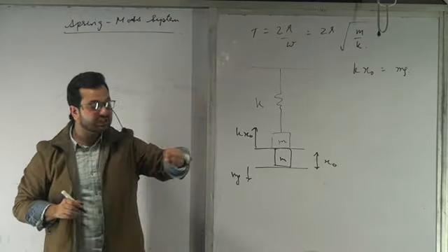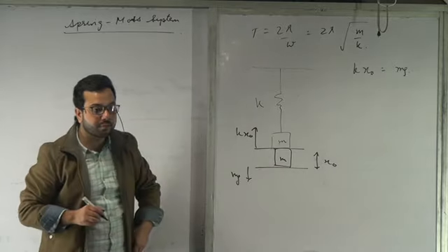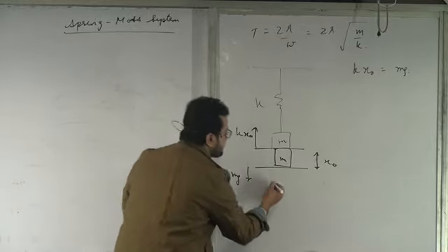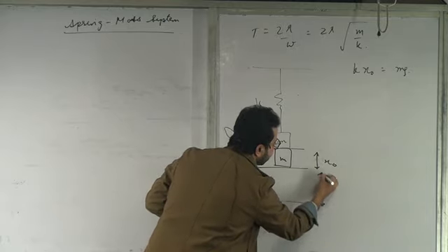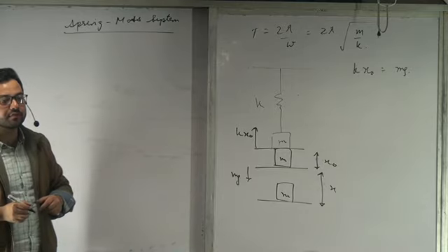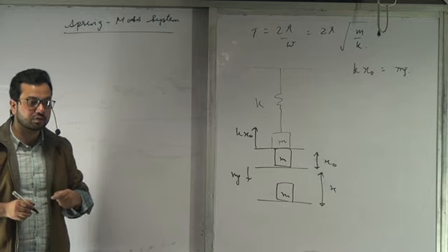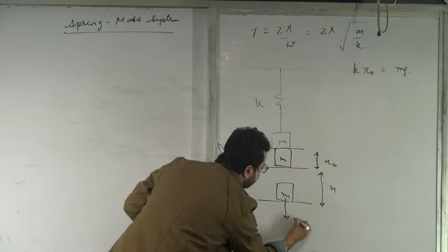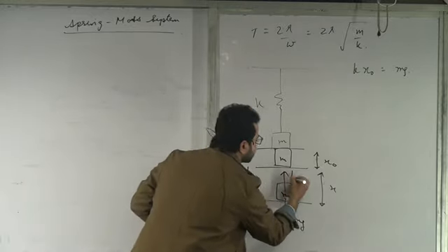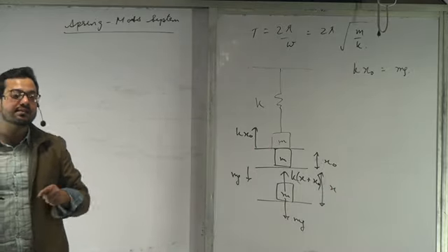Okay, now this is the equilibrium position, so all the displacements have to be measured from where? From the equilibrium position. So from this equilibrium position, I displace it further by a distance x. Now at this position, I need to find out the net force. Alright, so what are the forces acting? mg is acting. What is the spring force over here? Excellent. The force is k into x plus x naught, because the elongation of the spring now is x plus x naught.